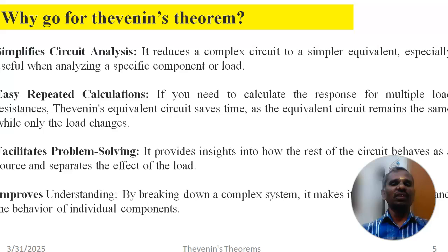Why do we want to go for Thevenin's theorem? This Thevenin's theorem simplifies the circuit analysis. It reduces the complex circuit into a simpler equivalent circuit, especially useful when you analyze a specific component or a load. It eases repeated calculations. If you need to calculate the response for multiple load resistances, Thevenin's equivalent circuit saves time, as the equivalent circuit remains the same while only the load changes.